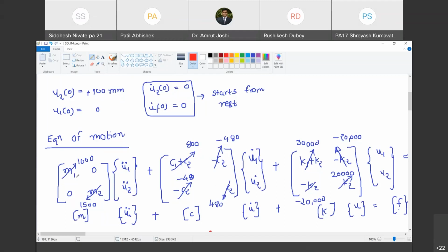Do you agree with me? Yes, sir. So in that case, if you have to model a load-bearing structure's response to a seismic excitation, you cannot go ahead with a lumped mass system. Are you with me? Yes, sir. Lumping the mass is feasible only for frame structures.